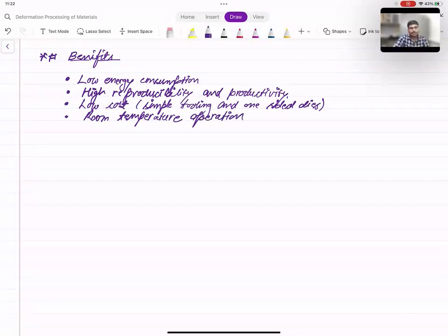And in this forming process, the risk of wrinkling or shrinking type of defects is very low. So no wrinkling is there. Also, the tool and job contact is minimum. No tool, job contact, as happens in case of other forming processes like forging, rolling, where we have the rollers which will be in contact with the workpiece. Here, this is not the case. So no tool job contact.